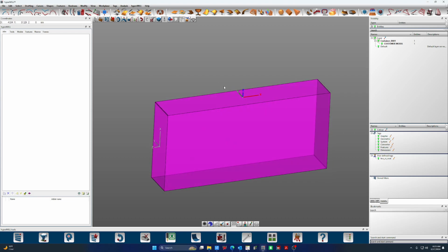What you need to understand is the tool paths you're getting, and I'm going to make a blanket statement here that I hope I don't regret. In just about every situation that I'm aware of, the tool paths that are being generated are with respect to your toolpath tolerances against the 3D model. The way it looks on the screen does not matter.